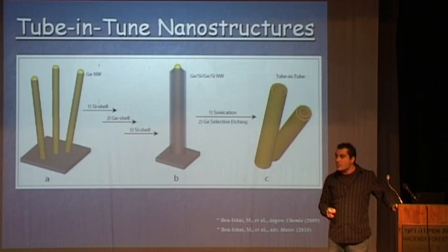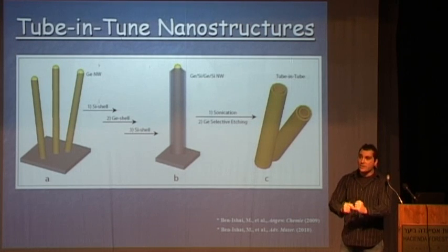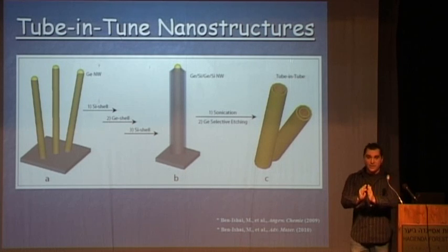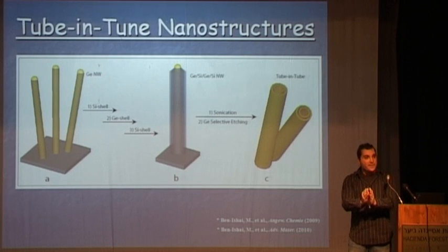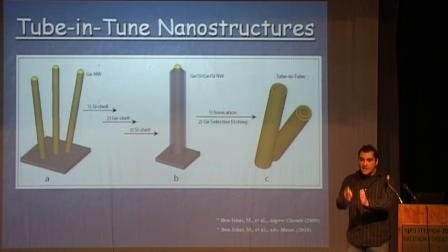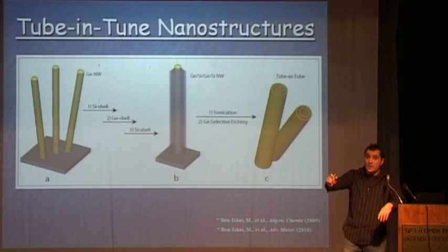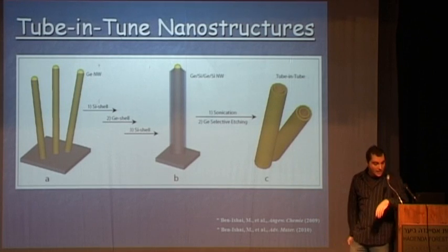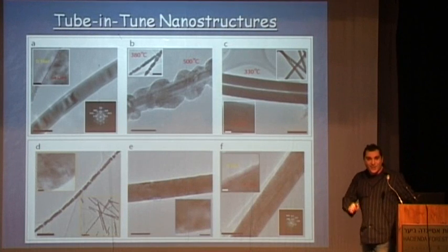Carbon nanotubes, multi-wall carbon nanotubes, or boron nitride nanotubes: we cannot control the distance between the walls. We cannot control the chemical composition and the dimension of each wall. In this case, by controlling the size of the germanium interlayers, we can create walls with a perfectly controlled distance between each tube. And we can create silicon walls with each wall having a different chemical composition and a different dimension. So we can see here, it was not easy to get to this point.